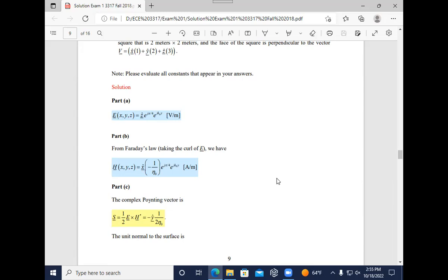And not only that, but this says partial of Ez with respect to x. But see, the Ez doesn't depend on x, right? So that one's gone for a different reason. So it looks like all this boils down to just unit vector x times partial of Ez with respect to y. All right. So therefore, it looks like H is equal to -1 over j omega mu 0, unit vector x, partial of Ez with respect to y. And of course, all this here is Ez.